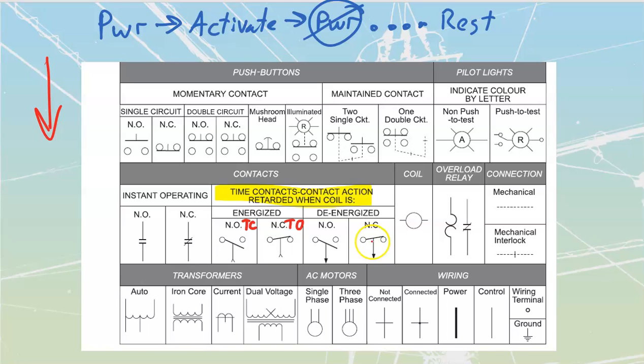Let's look at this one over here. Once again, when we apply power, it will instantly activate. Boom, it's going to push open like that. Then it's going to stay open for as long as we apply power, but when we take that power away, then it's going to start timing. Tick, tick, tick, tick, and then, boom, go back down to the rest position.